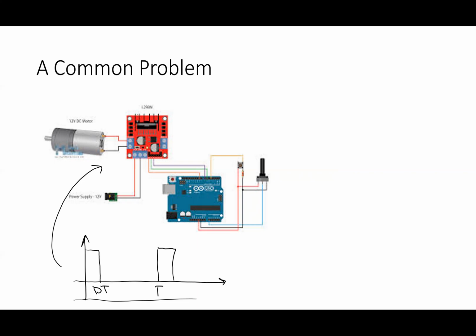All a motor driver is, fundamentally, is something that takes a little weeny square wave that comes out of a microcontroller and basically beefs it up, which is a very technical term, meaning that more current can go into the motor, more amps, okay? I need amps for motors. Microcontrollers can't give me amps. Looking at this picture, you may have heard this term before. What I have here is a PWM wave. The microcontroller generates this nice little waveform, a simple square wave.